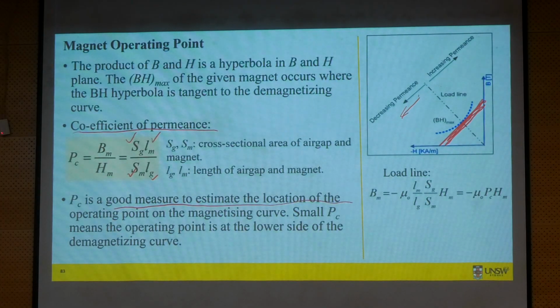Some other material like Alnico can be easily magnetized and demagnetized. So if you use those types of material and you can switch your magnet on and off through control, only then could it move to the other side, okay. But for the conventional neodymium iron boron type of design, it always operates in the second quadrant only, okay.